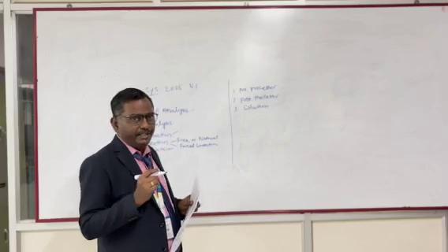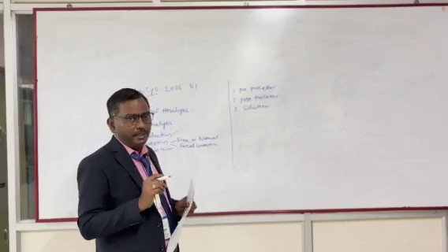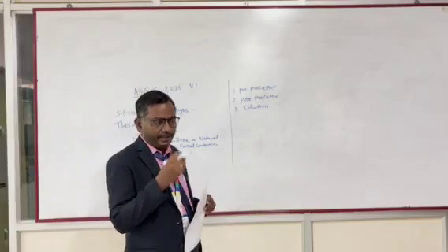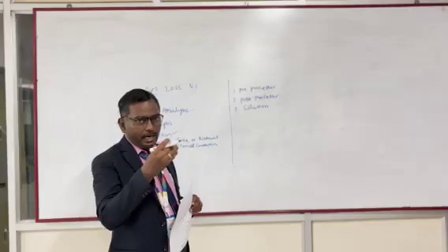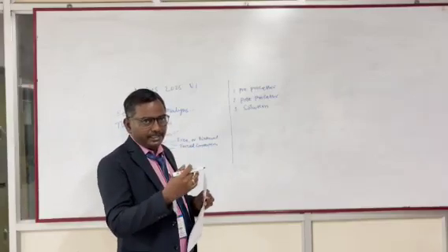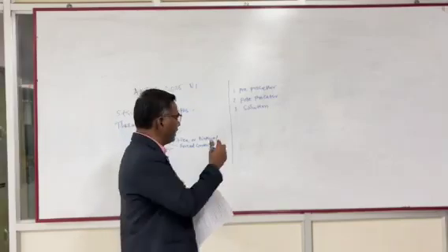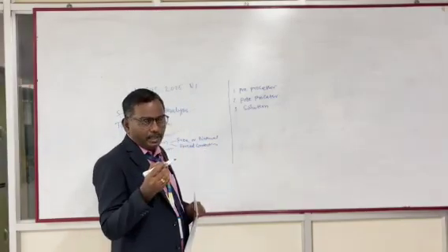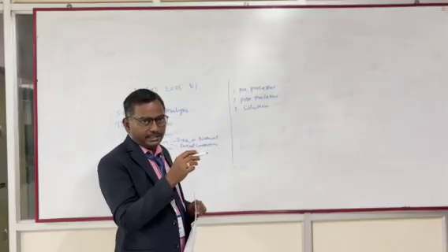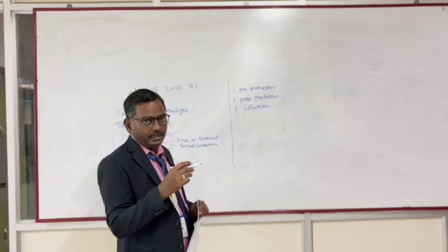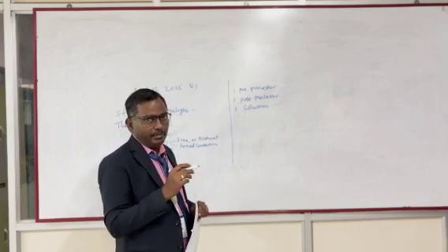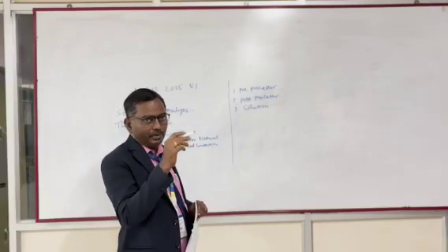Result finding. After giving these, we have to give the analysis type, which type of analysis, whether structural or thermal analysis, whatever type of analysis we have to give as an input. Then, at the next step, for the given problem, we are going to check the load conditions and other constraints. All of these we are going to check in the solution type, and then we are going to solve by giving the solve command. So automatically the problem can be solved.